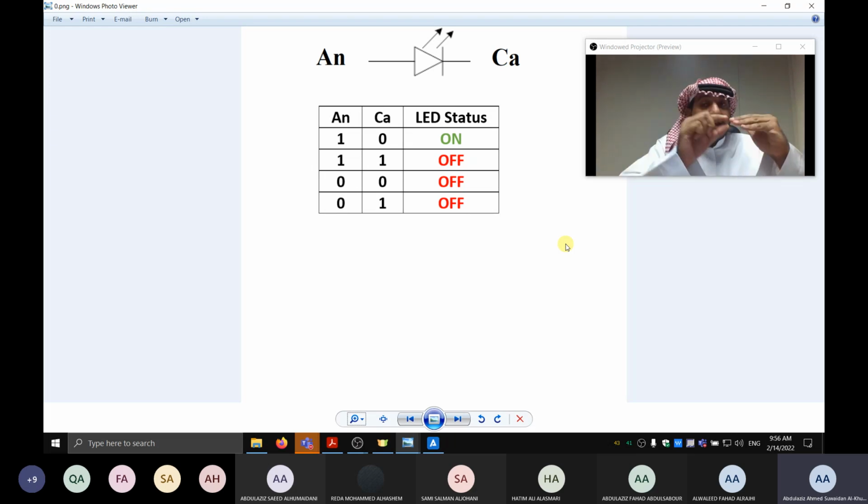Anyone with experience, can you tell me what's the value of the resistor typically? It's supposed to be 220 ohms. Normally, typically, they purchase an LED light and then they put a 220 ohm resistor in series with it. Why? Because it needs to protect the LED itself.